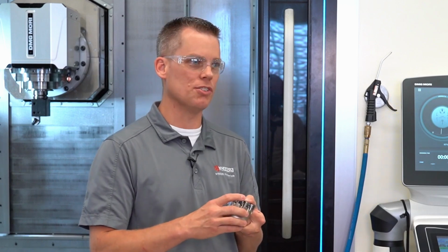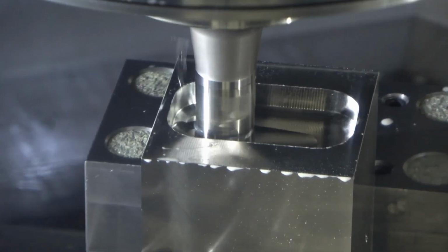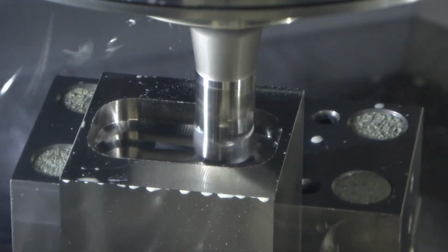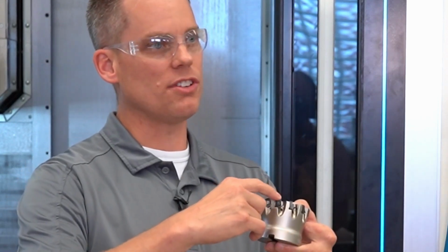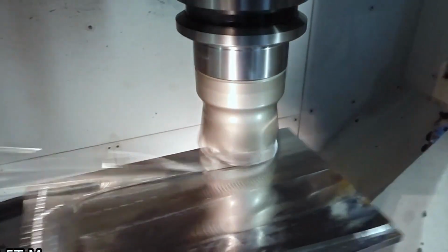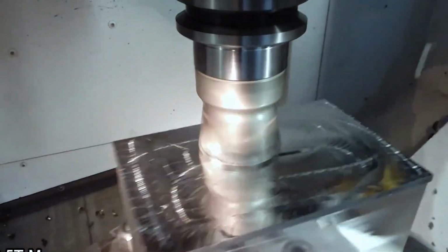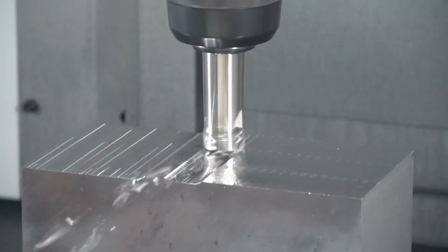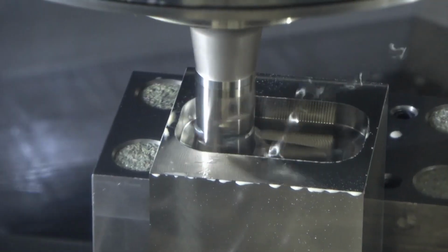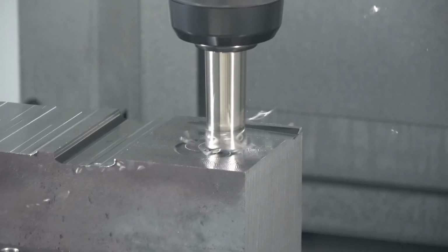Let's talk about high feed mills next. High feed mills are incredibly useful roughing tools, not necessarily used for finishing operations, and they're really only useful in CNC machines. High feed mills operate on the principle of a chip thinning process, which is to say that each insert has a lead angle that can be fed extremely fast into the workpiece, which thins out the chip, allowing for a much higher feed rate. A few of the applications where you might want to apply a high feed mill in your roughing operations are 3D surfacing, slotting, ramping, pocketing, cavity machining, plunging, and helical interpolation.